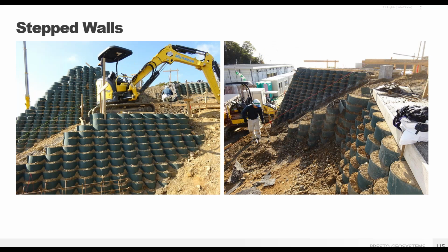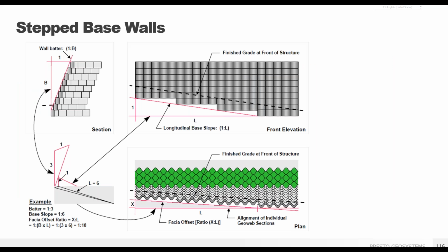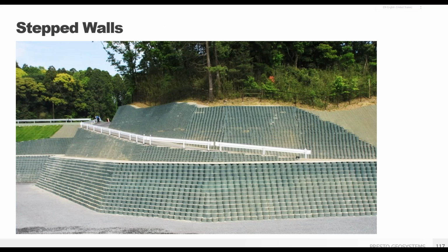Stepped walls are a bit of an advanced install, needing some technique and some extra planning. Our full installation guide gives examples of calculating offset dimensions for a GeoWeb wall on a stepped base. Useful for interesting walls such as this. The engineer used 3 different wall batters and multiple stepped areas to make the GeoWeb fit the site.